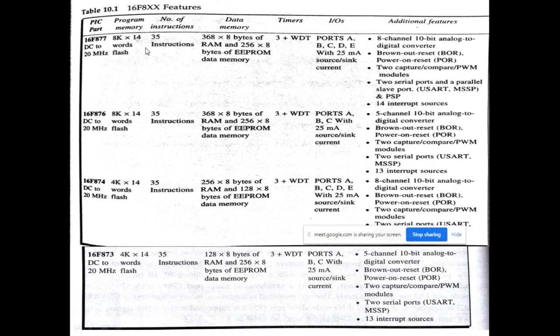This microcontroller additionally contains an 8-channel 10-bit A to D converter. So ADC is inbuilt, and it is a 10-bit ADC having 8 channels. So it is possible that you can connect 8 different analog input devices to this microcontroller, and you can convert the analog input from each of those devices into digital equivalent, and that can be processed further.